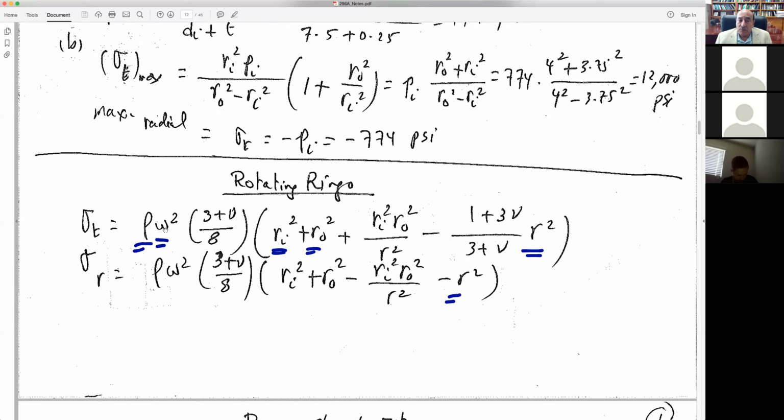One other point I wanted to bring to your attention is that if you're using the US customary system, the density is not going to be in kilograms per meter cubed. You have to convert it to pound force, because this has to come out as something in force. So you have to equate the mass times the acceleration of gravity to the force. You get a conversion that uses gravity in the British or US customary system, which is 32 feet per second squared. The foot also has to be converted to inches, so it becomes 386 inches per second squared. So you get a factor that is important here to determine this maximum RPM correctly.